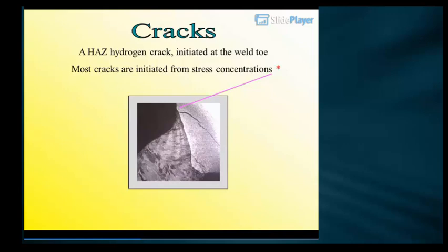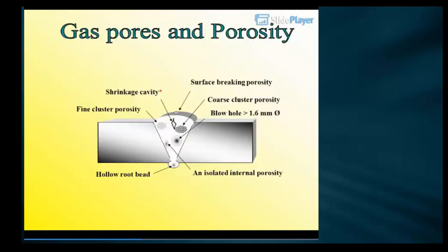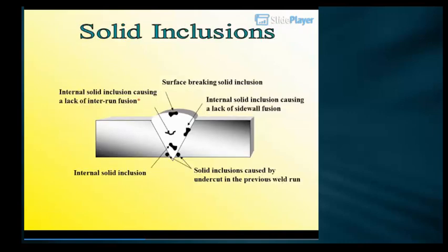Most cracks are initiated from stress concentrations, surface breaking porosity. Gas pores and porosity. Surface breaking porosity. Shrinkage cavity. Coarse cluster porosity. Fine cluster porosity. Blowhole greater than 1.6 mm. Hollow root bead. Isolated internal porosity. Solid inclusions. Surface breaking solid inclusion.